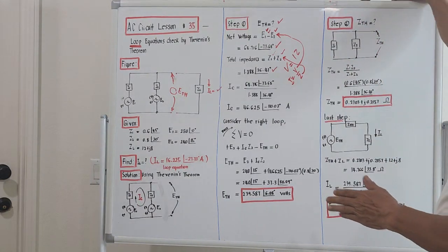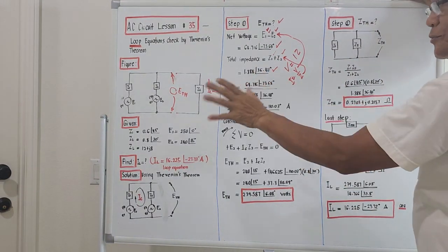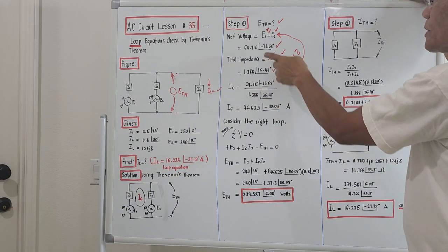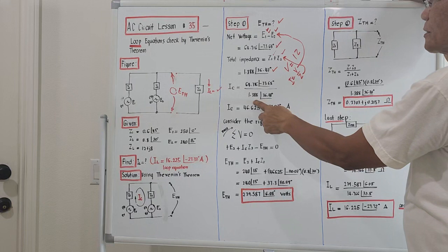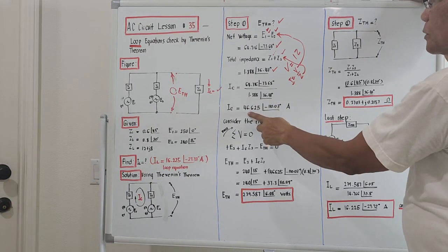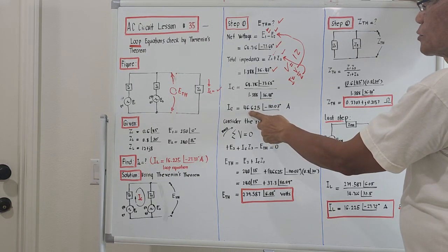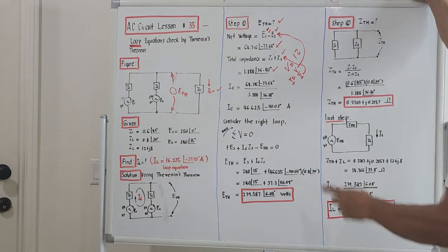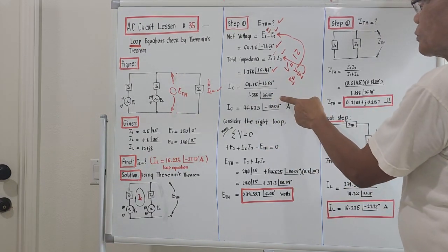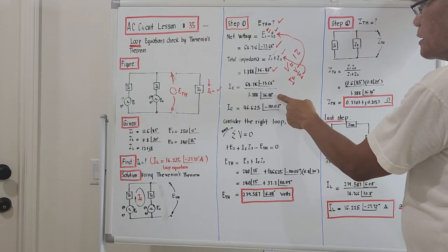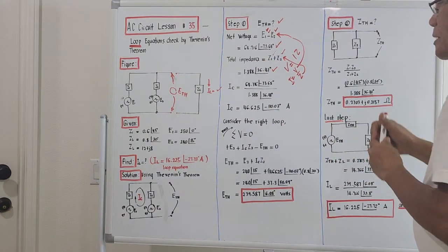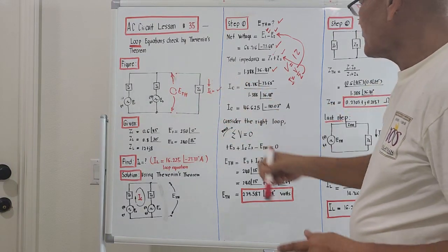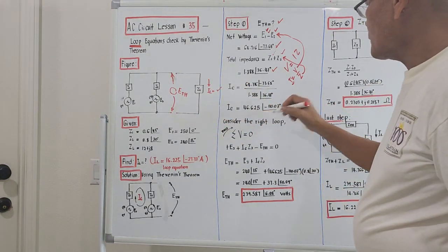So the circulating current after the disconnection will be the ratio 64.716 over 1.388. What will come out will be 46.625. The angle will be, a minus and a minus, so it will add up: negative 110.03 degrees, amperes. So after the disconnection of C sub L, the circulating current within the system is 46.625 amperes.